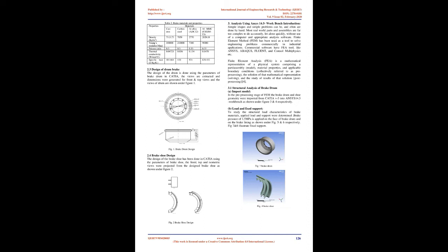The material used for the brake lining should have a high coefficient of friction with minimum fading, in other words, the coefficient of friction should remain constant over the entire surface with change in temperature, low wear rate, high heat resistance, high heat dissipation capacity, low coefficient of thermal expansion, adequate mechanical strength, and it should not be affected by moisture and oil [5].